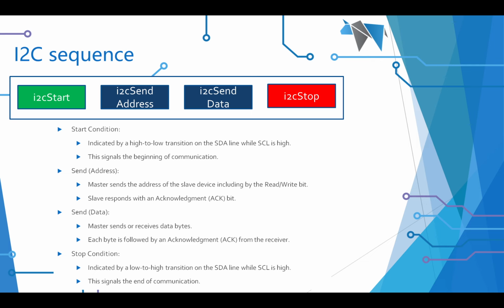And we have a set of public I2C commands: I2C start, I2C send, I2C stop, I2C restart. And they're all in the help. So we're going to see them live, but if you want to know what the software ones are, they don't start with H. All the hardware ones start with H.